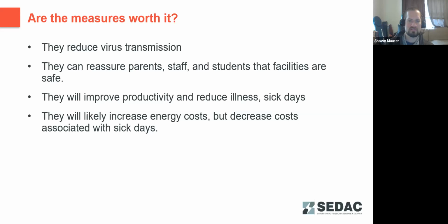Looks like most people have answered our poll questions. Let's just review that quickly. MERV 13 is the correct answer. That is the minimum filtration recommendation. Looks like most people got that answer correct. The 800 parts per million CO2 target does ensure adequate ventilation with minimum energy impact. If you're increasing beyond that rate, you're having a drastic increase in your energy costs for fresh air ventilation without a great impact on the quality of the air in the space.